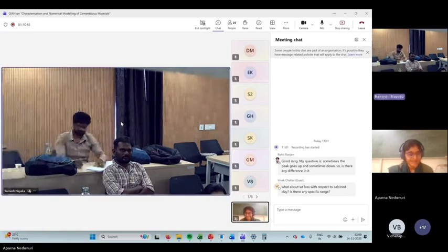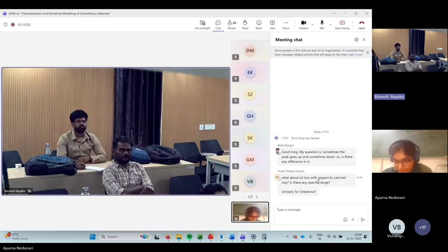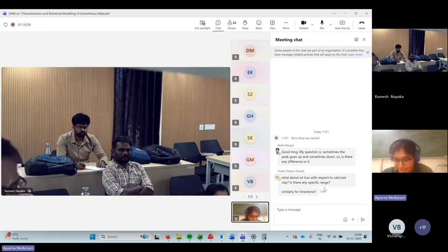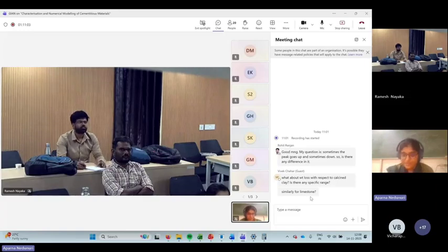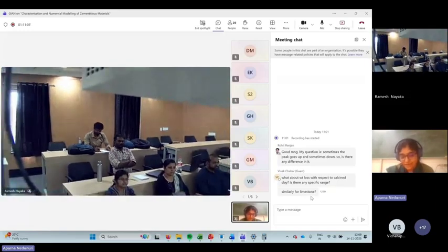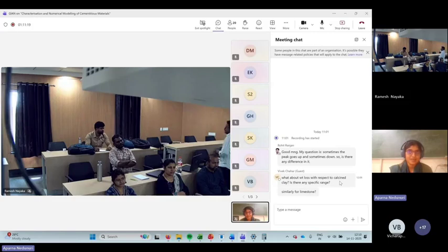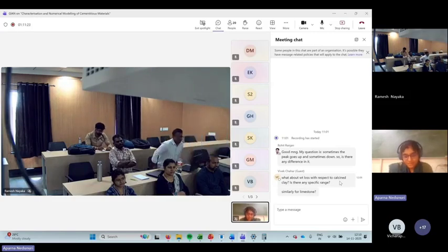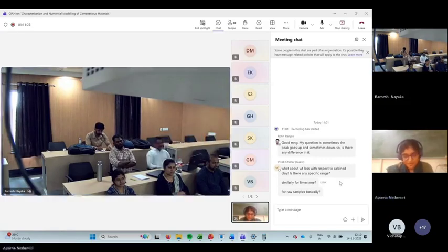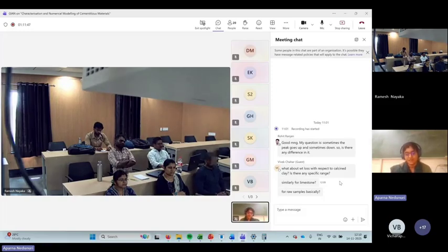Ma'am, there are a few questions in the chat box. What about weight loss with respect to calcined clay? Is there any specific range? Similarly for limestone, which is basically calcium carbonate, you will have decarbonation that can be seen in different temperature regions, depending on what type of carbonate is present. So there will definitely be a weight loss. Even in calcined clay, if you are talking about metakaolin, you will still have some amount of dehydroxylated systems, and that dehydroxylated water is always visible as a weight loss at different temperature zones. So it's not that we have to do TG only on hydrated material. Always prefer to do TG on the raw material and eliminate those weight losses from your hydrated material, to see the actual amount of hydration that happened in the system.